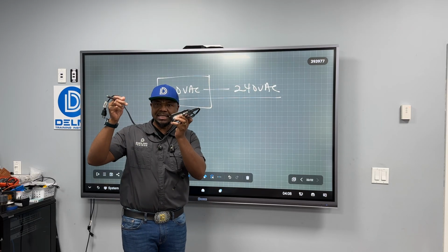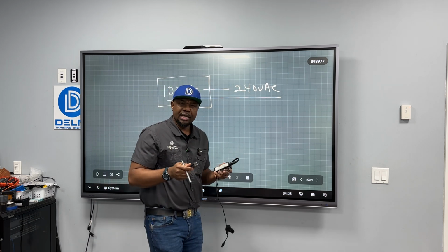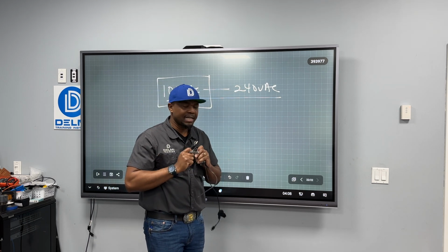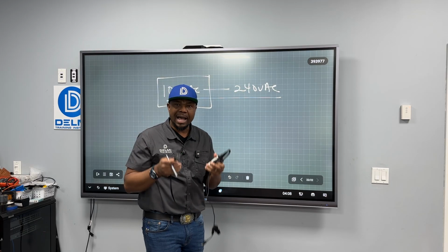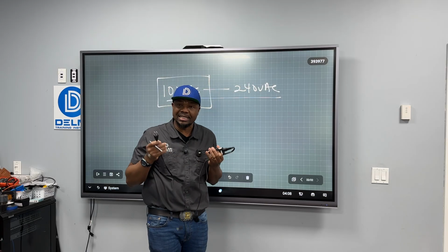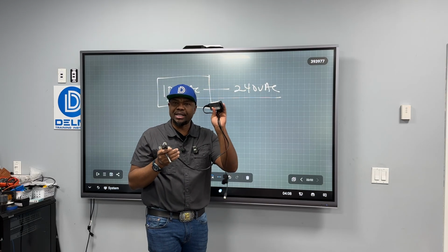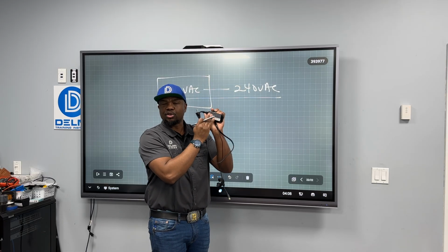But this has only been designed for 210. So what is going to happen? He's going to receive the laptop in Uganda, and he's going to be so excited. And in the quest to have it working, he's going to plug it into this 240, and that's a high voltage. Right away, he's damaged this, and the laptop is not going to work because he just destroyed the components in it.